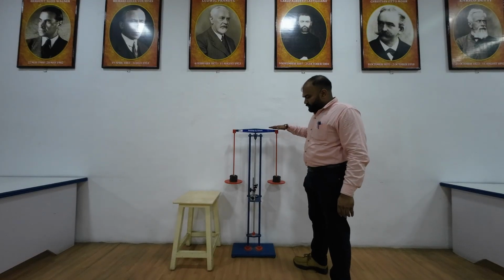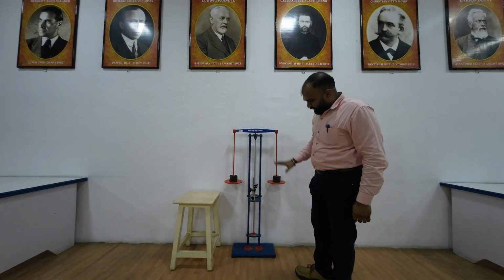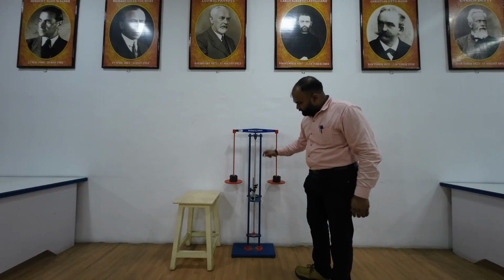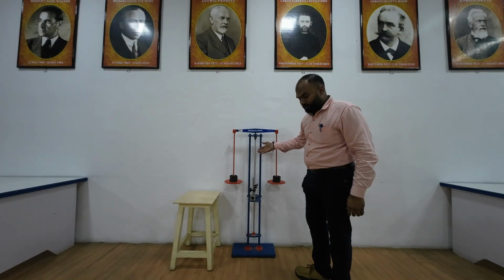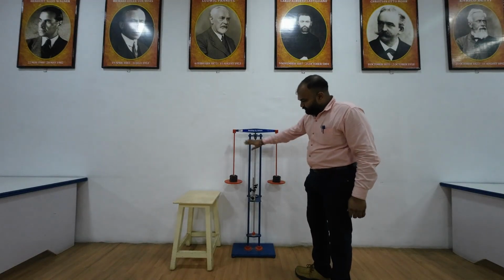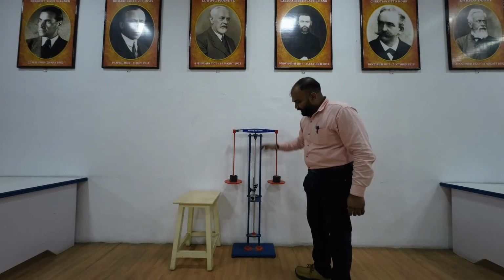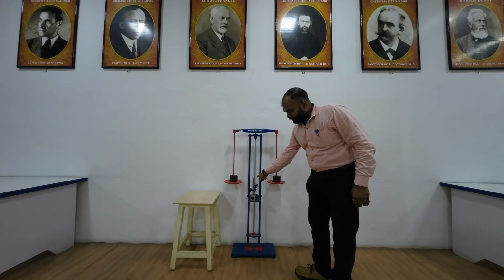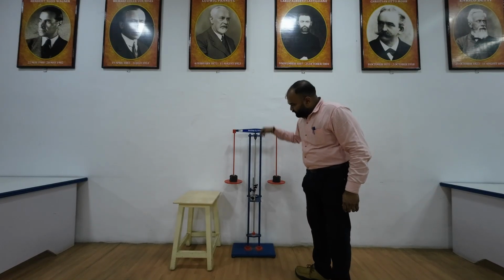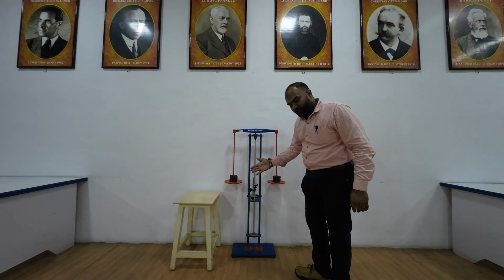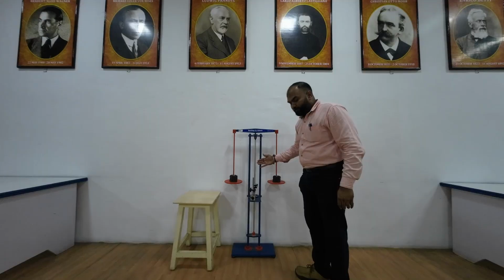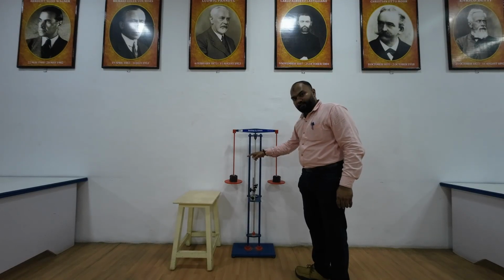We have a setup for testing buckling of columns. This setup consists of a frame where we have the pin ends where you can place a column of various materials. You can test it here. Presently we have a column made of aluminum, and then we have weight hooks which act at the center when you apply weight, and a dial gauge pointing onto the column. When you apply load, the column bends in this direction or in this direction. So we will be able to measure deflection for the given applied load.